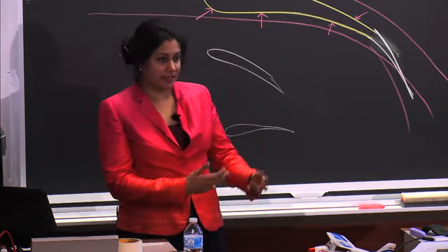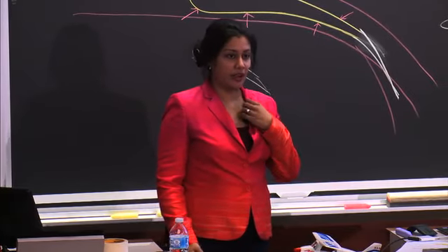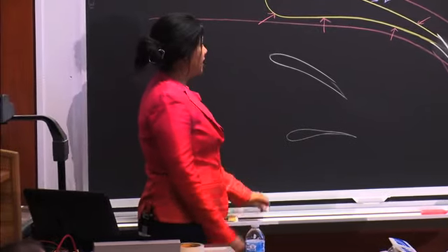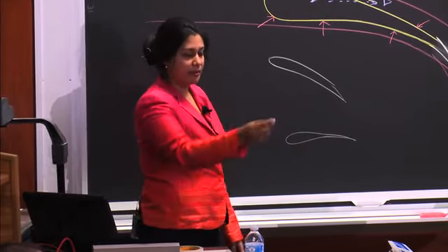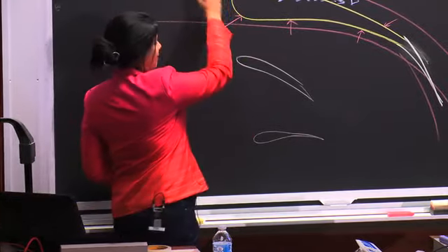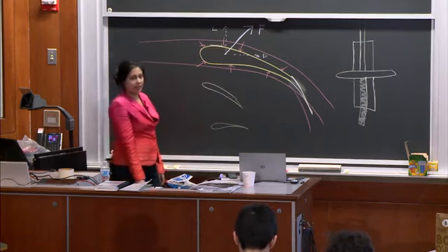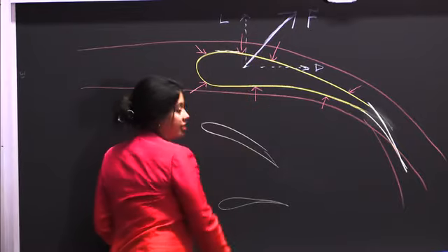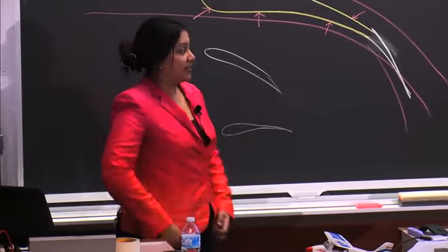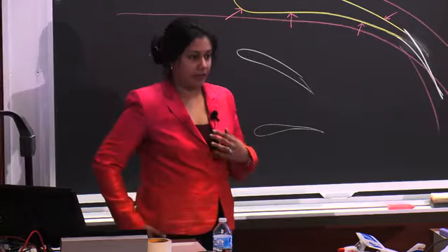So it's the tendency for these molecules to stick to each other and to stick to the object that's moving through them. With the case of the airfoil, we were discussing this just a moment ago, about which air were we talking about. Some air that might be very close might kind of stick to that airfoil or stick to the wing versus just moving smoothly past it. So viscosity has a big impact. And then compressibility also affects lift. So the compressibility of the air.